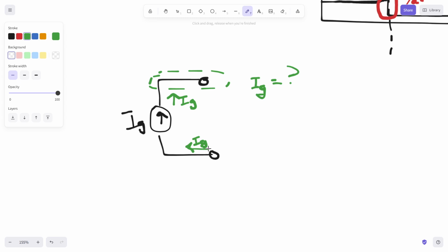Well, it has to come from somewhere. It has to pass through both ends of the channel. This is that current coming from somewhere else in the circuit, entering a certain point of the circuit. And in reality, you've got some kind of loop that's occurring here throughout the rest of your circuit. But this is an important concept to understand, that your current source is just forcing a specific current through this branch.